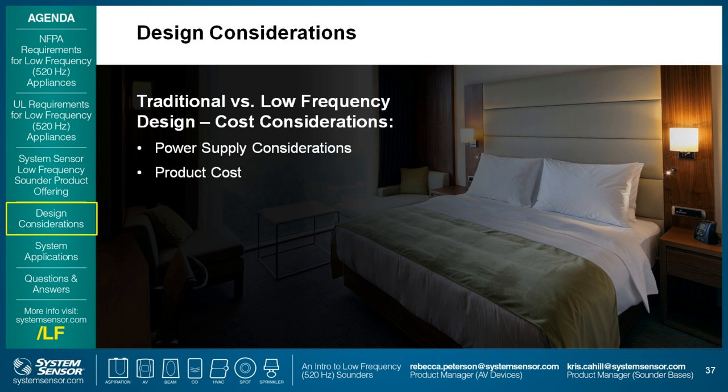And as I mentioned before, those products utilize a piezo element that draws very little energy and is relatively inexpensive. With the new low frequency requirement, at least for our product solution, we found the best way to meet the requirement was to utilize the speaker element. And speakers inherently draw more energy, compounded with the fact that a square wave signal format is required that also requires more energy, these low frequency products draw significantly more current than a standard product. This will impact the amount of power supplies you will need to meet the sleeping space requirements. And since we utilize a speaker to meet this requirement, the product also costs more than our traditional horn products. So by nature, more current draw and a more expensive device. This is something you want to keep in mind when you're planning your systems and laying them out.